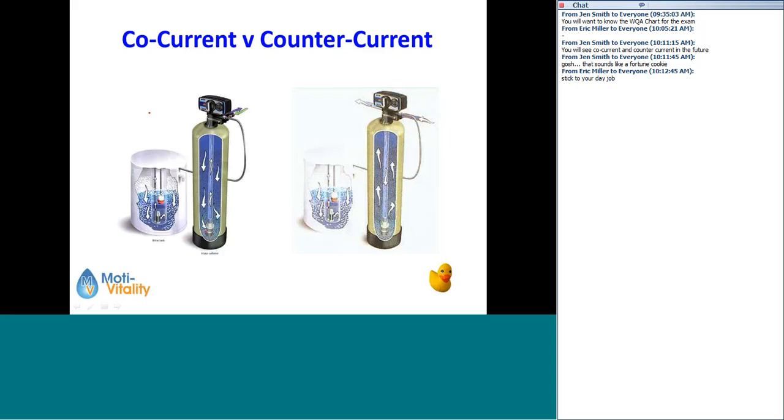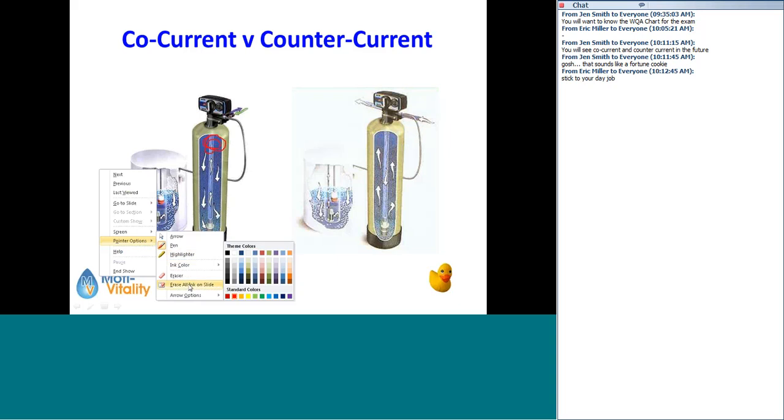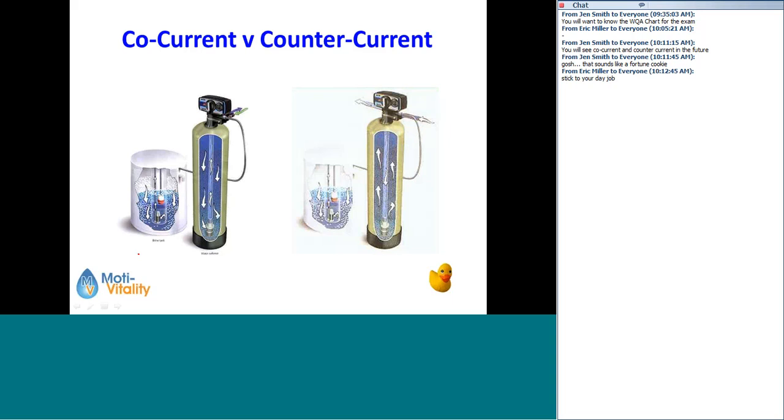So anyway, freeboard. This area all up in here, this is all fresh water. So if you're cleaning co-currently, this is why a water softener with countercurrent regeneration is so much more efficient. You make the brine down here. Let's say you've used 8 pounds of salt and you've got a fully saturated brine solution, and you suck that in through the brine valve, and it brings that brine in.